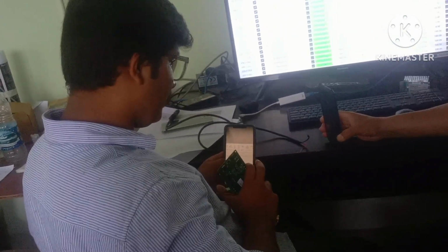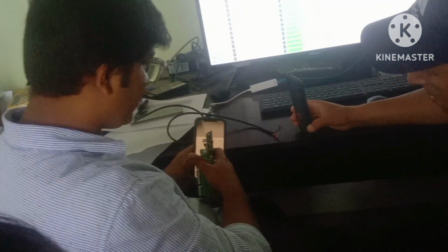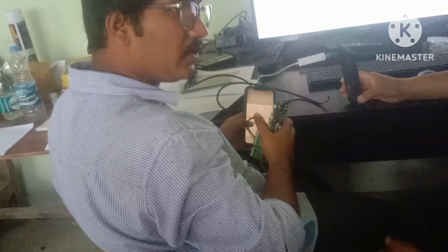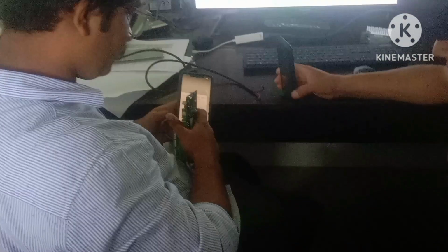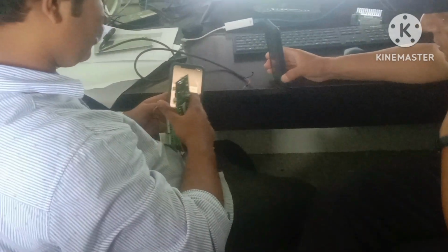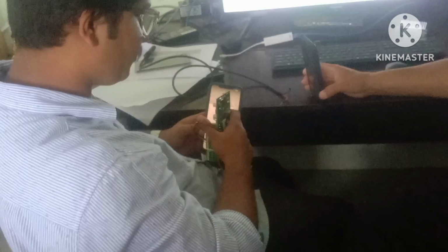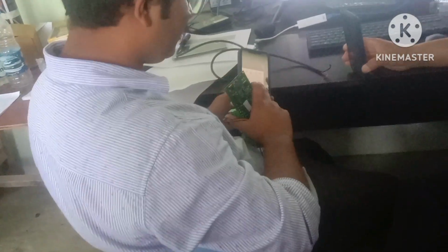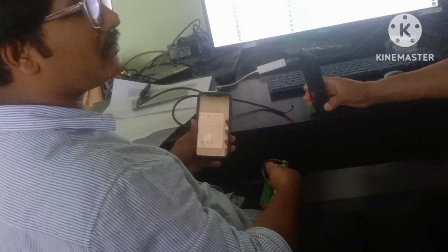Then there is a spare DI given, so this is a spare DI. Then there is a temperature sensor which we are seeing, the actual temperature. So the temperature sensor is wired here, 25, 26. Then there is a spare AI. This is also a spare, and this is where the Modbus RTU, like I told you, A and B, positive and negative, is connected, positive to 30 and negative to 31. So this is what is inside the control.